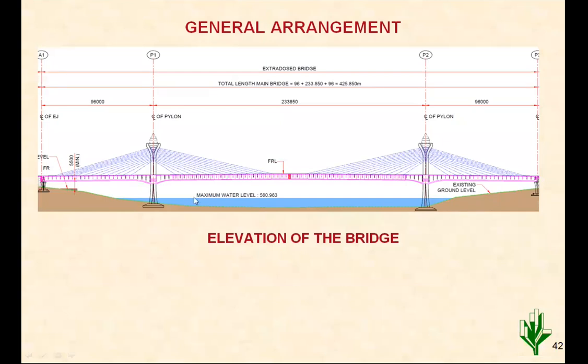That is, for understanding the difference between the two cases, that is extradosed and cable-stayed bridge, it is mainly because of the force transfer mechanism. In case of steeper cable, that is almost vertical cable, more force is transferred through the cable itself and lesser through the deck. Whereas in this case, the deck is also steeper.